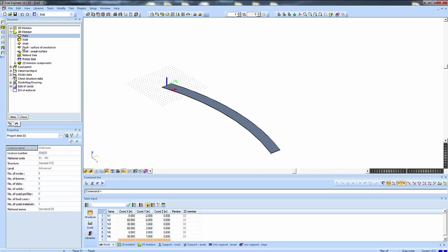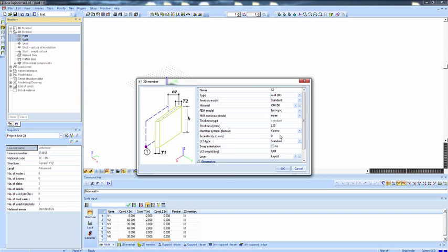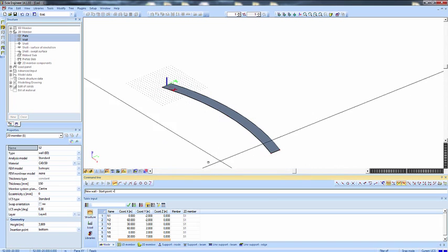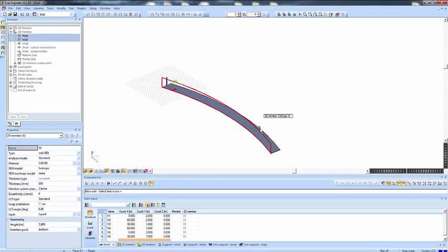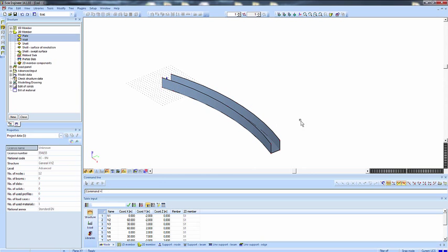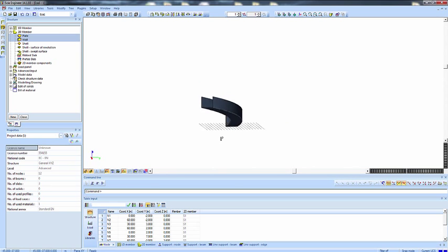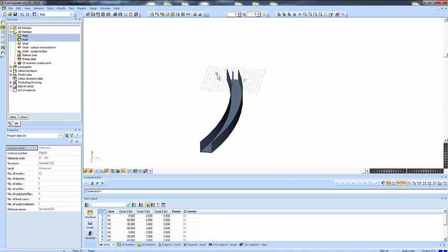And actually, if I want to model a plate or a wall, for the solver in the end, it doesn't really matter. But a wall is easier to input as vertical elements. Let's say I'm going to input a wall which also has 150 millimeter of thickness. And I can even choose to a line. That option will allow me to just click on a line. The wall will be placed over that line, just like that.